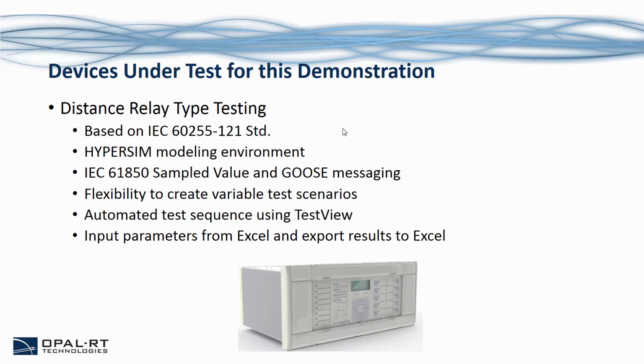In this demo, we're using the IEC 61850 sampled values and GOOSE messaging to communicate with the relay under test. And we're using a model-based design and testing methodology just to create more realistic testing scenarios.